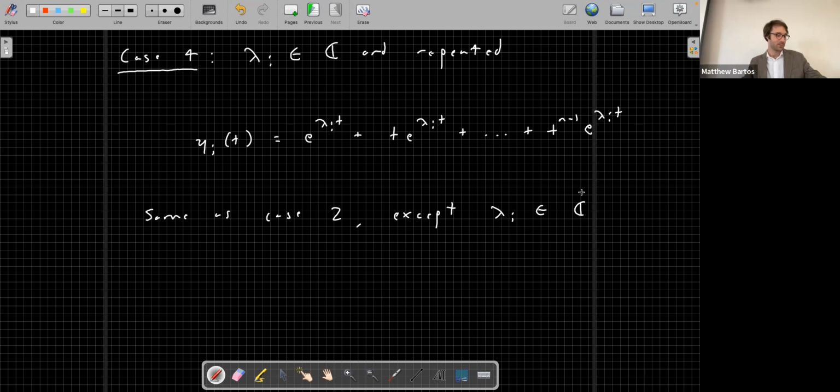Okay. Are there any questions on the different response types that I presented for you today? Okay. So key takeaway points here. The response of any LTI system is some linear combination of the 4 different cases that I've shown you here. So when you're solving an LTI system, you solve for each of those roots, you determine the individual responses corresponding to each root, and then you add them together. And that will give you the ultimate response of the LTI system.